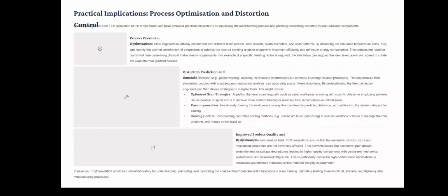The temperature field simulations ensure that the material's microstructure and mechanical properties are not adversely affected. This prevents issues like excessive grain growth, embrittlement, or surface degradation, leading to higher quality components with consistent mechanical performance and increased fatigue life. This is particularly important in high performance applications and aerospace and medical industries where material integrity is critical.